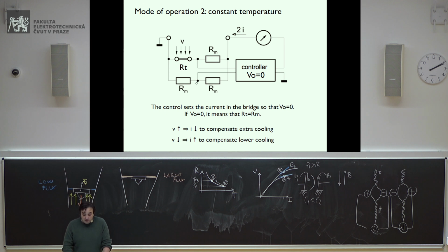Well, you use this bridge. Again, this is a bridge even if it's drawn horizontally, but it's the same system as vertically. So we have 4 resistors. 3 of them are resistors which do not depend on the temperature. They can be outside the pipe, basically. And they are constant resistors at the value of the resistor that you want to keep the thermistor at. For instance, let's say that we want to keep the temperature here, and we select 3 resistors of the bridge corresponding to RA.